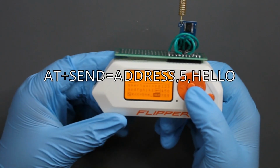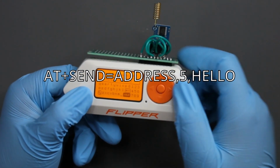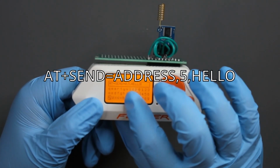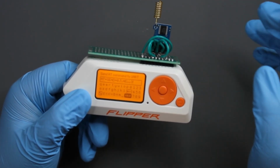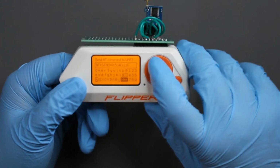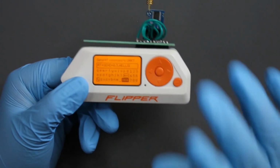So I'm going to write down the code on the screen so you can copy it. And that should be the code: AT plus SEND equals the address that showed up on the other thing, comma, how many letters are in the word, comma, and then whatever word you want to type. No spaces at all. Once you hit save, it's going to send it to the serial monitor if you did it correctly.